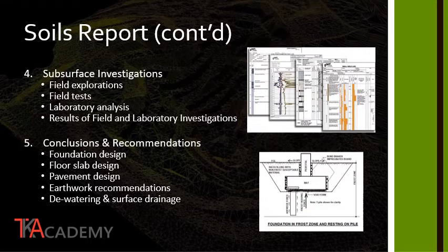The fourth part of a soils report will include the findings of the subsurface investigations. This will include the field explorations and tests, which are typically documented in the boring logs. This part of the report will also include the findings from the laboratory analysis. This section concludes with the results of the field and laboratory investigations of the soil samples.